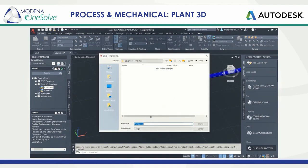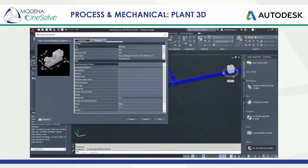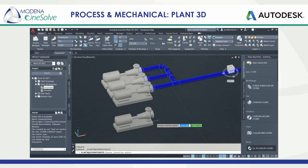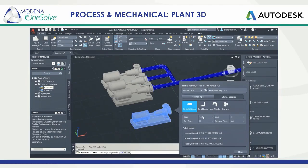You can, at this stage, export this piece of equipment out as a Plant 3D piece of equipment, and this allows us to leverage this configured model in the current or in new projects. Once saved out as an equipment template, it's very straightforward to bring that back in. It's a matter of creating a piece of equipment based on the template, and there you see how the data has come back through and how the nozzle information has already been defined.